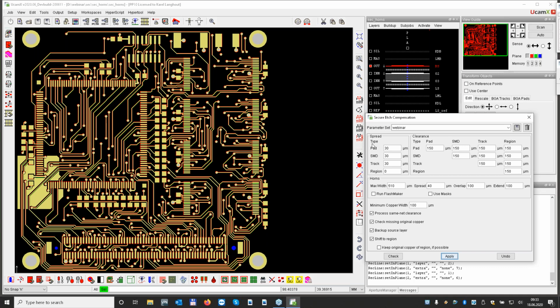Another one would be based on the flashes. Which pads are getting horned? First of all, we have our width, and the width is then taken and checked against every box and rectangle that there is in the data. Those pads that fall into these criteria will get horns.